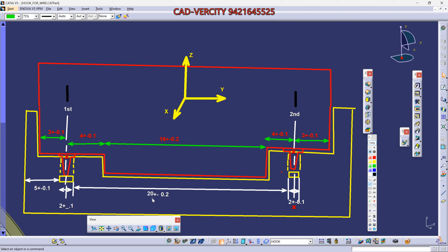Okay, you are calculating from the center. No, I want this dimension in the red part. Oh, okay, sir. 24.4 is maximum, let me note it down. So in the red part, the maximum dimension is 24.4, sir, and the minimum is 23.6. This will be min.